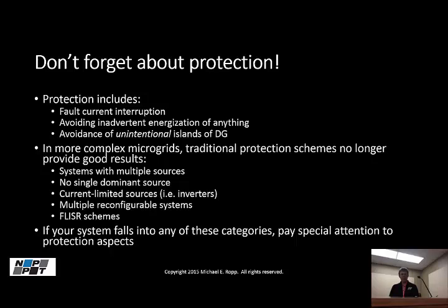There are some cases where the battery inverter system might be significantly over-designed relative to the load, so that your maximum load current and your fault current might be far enough apart that there's still room to put TCCs in the middle. Sometimes you can get away with it.